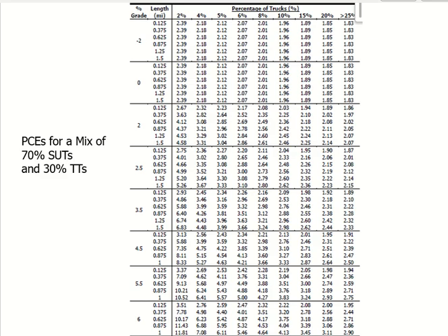They said, okay, if you have negative, take it as a level terrain. They said, you go back to the small table and take the value of level or rolling terrain, one of those, which is very close. If you see the value for level terrain, it is 2. And what is the value here? 1.96. If you look at all these values, they are around 2. But obviously they want to be more accurate, more precise.